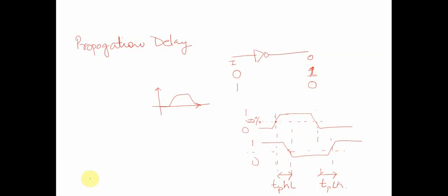correct? So now, what kind of IC family would we prefer in case of propagation delay? Ideally, we want any change in input to be reflected on the output instantaneously. Basically, instantly, it should reflect on the output. What would this mean? We want to make sure this trends to zero. That would mean lower the propagation delay, better the circuit,